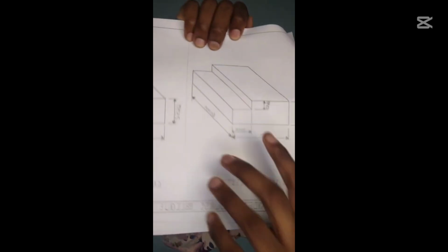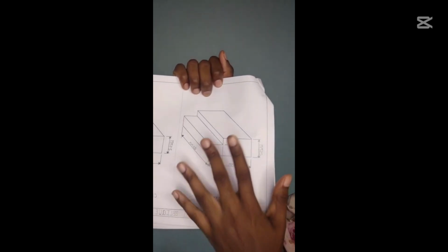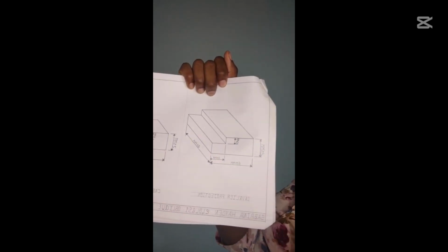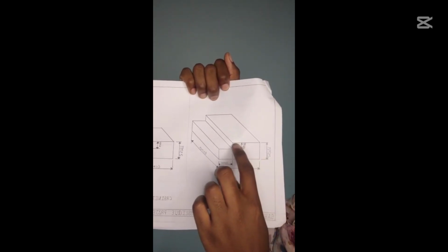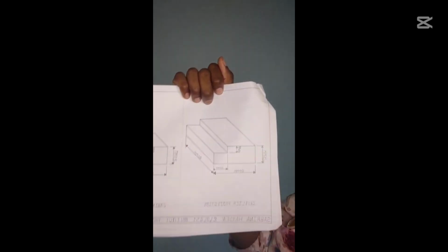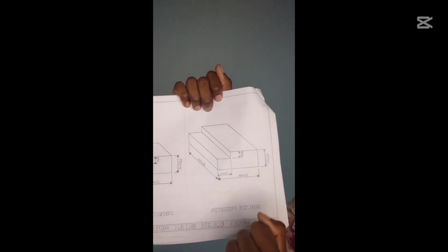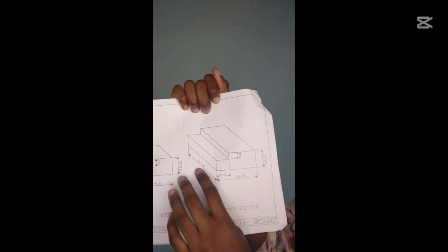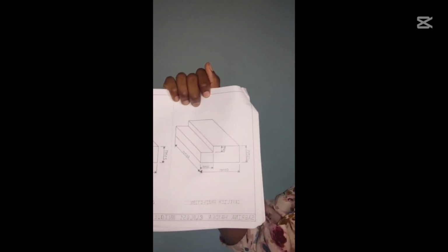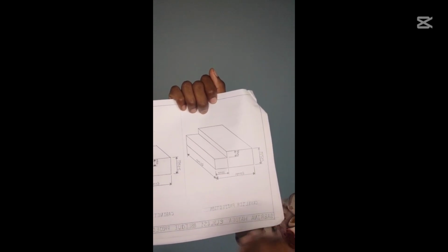Okay, so this is our Cavalier projection. It's upside down. Cavalier projection. So in this, we have the face at first. So this is what you're going to draw first. I'm going to demonstrate to you in AutoCAD. But this is what you would draw first, the face. And then from all the corners, you would draw your 45-degree lines to whatever length it tells you to do it. Now, with the Cavalier projection, you have the full length of the 45-degree line.